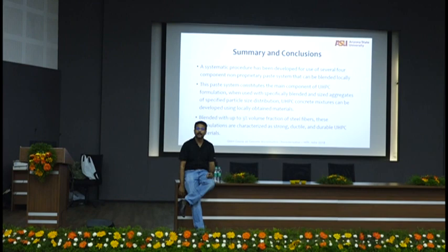And eventually, at 90 days, they got close to 200 megapascals. We got about 175 in the lab. In the field, they got 200 megapascal because their field mixers are much better than the lab mixers. In the lab, I have my big lab rotatory mixer, but in their field mixer, with all the mass that goes in and the resolution, they had a much better mixing, and fibers distributed really nice. Or about 192 megapascal or so, at 90 days, which is way more than what was specified. They wanted 150, they got 150 at a fraction of the cost that they would have spent.